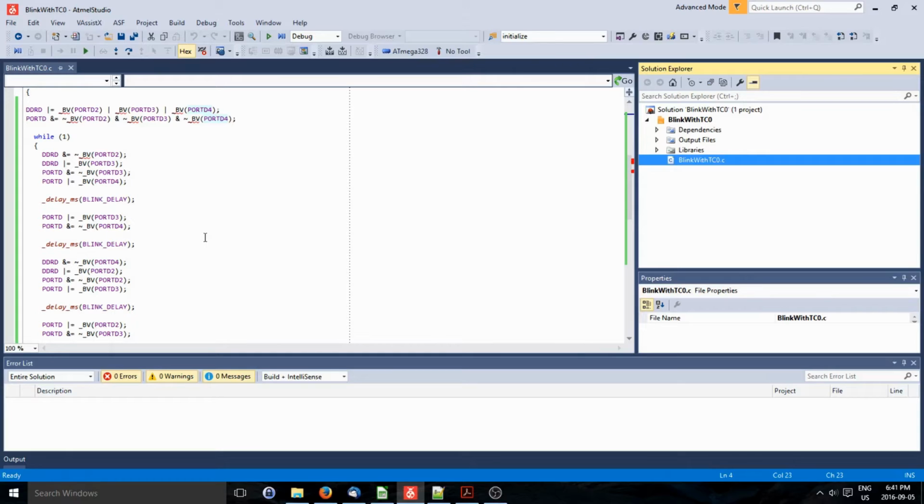Now this is of course an incredibly simple piece of software here, and it's doing nothing but blinking the LEDs. So I'm just showing you how to break up a process into chunks so that you can do other things. Remember, the microcontroller, there's only one brain in this thing, only one CPU, so it can only do one thing at a time. So it can do a little bit of one thing, put it aside, and then do a little bit of the next thing, put that aside, and go on and do something else.